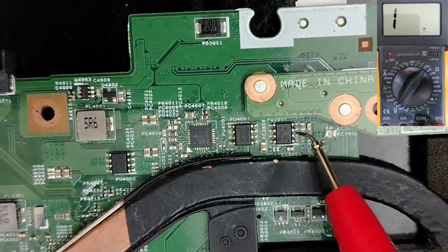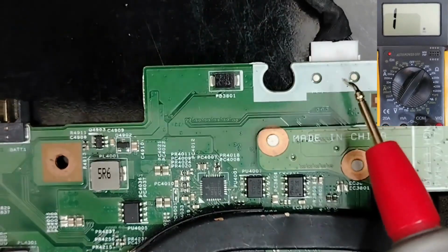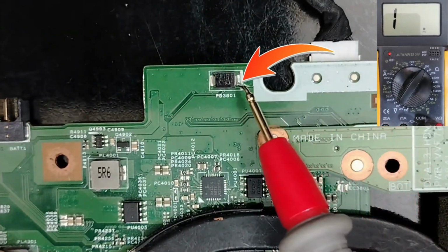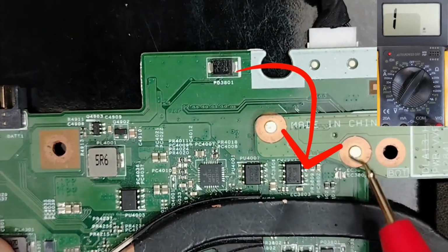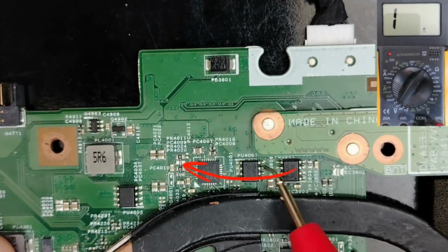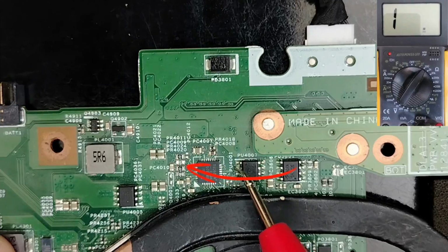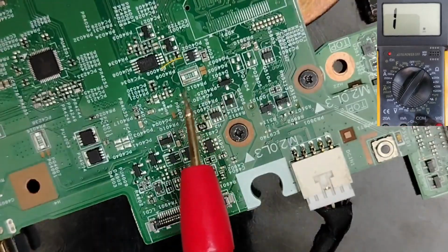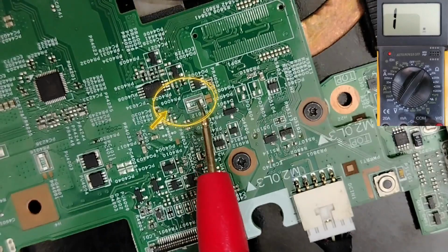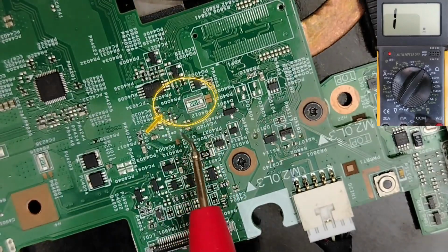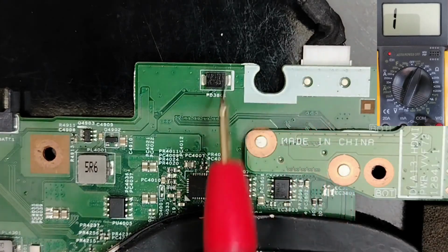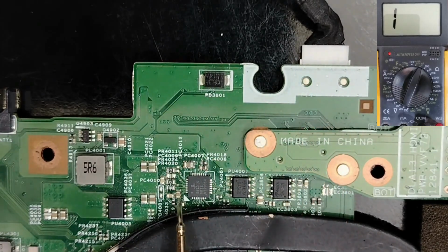And also pay attention to switches. Here for this board we have two switches, because the voltage will pass in this direction through this diode, then through this MOSFET, and then through this MOSFET, and then goes where? Goes to here, to this current sense resistor, guys, and then it will be distributed to all circuits in the motherboard. I can even prove to you this part, guys. Please pay attention, very important and very exclusive.